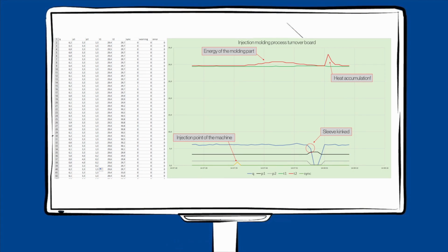In this example, a mold circuit was connected to our D system via the digital input and has been logged for 1 cycle. Here you can see the synchronization signal with our D system. The heat transfer in the mold increases the return line temperature. Shortly after, the flow stopped; at the same time, the supply pressure P1 increased and P2 collapsed.